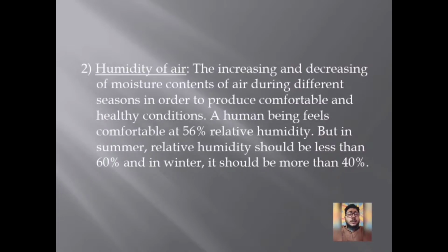Humidity control means an increase or a decrease in moisture content inside the space to be air conditioned. It is necessary not only for human comfort but also to increase the working capability. In summer the relative humidity should be 60%. In winter it should be 40%. Humidity is also an affecting factor, because if water is heated and it evaporates to the surrounding environment, the resulting amount of water in the air will provide humidity. Relative humidity is the ratio between the actual amount of water vapor in the air and the maximum amount of water vapor that the air can hold at that air temperature.